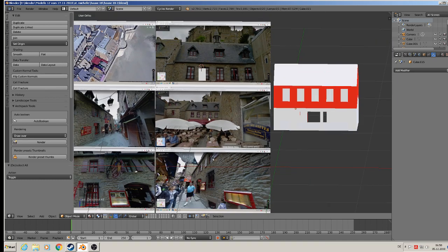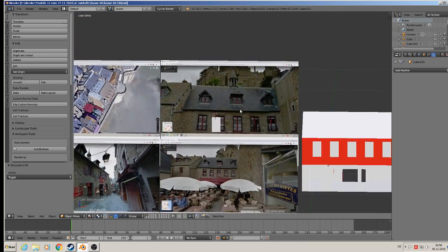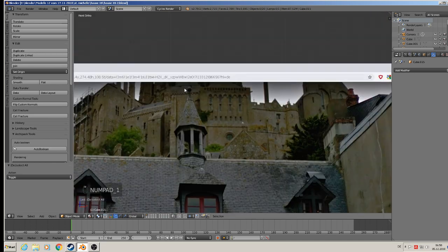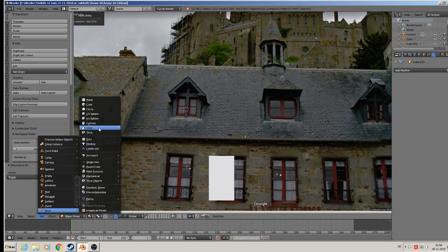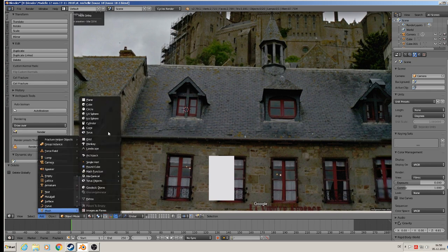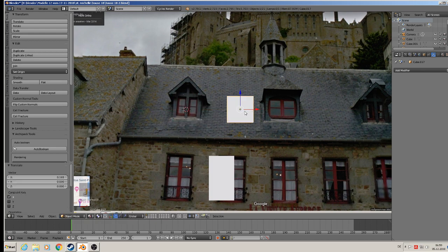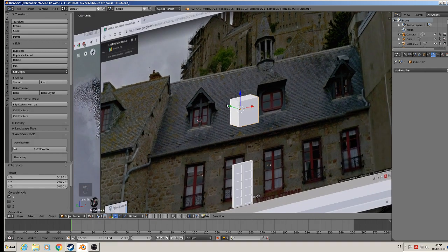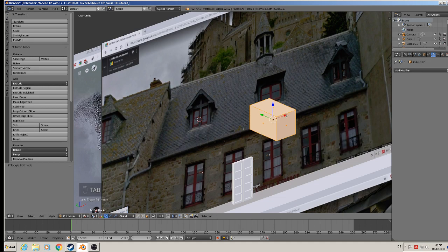So we need this rooftop style there. Here 3, and on the other side 3, and the middle one is different from the ones on the side. Okay. So we start again. Add mesh, not plane, cube like ever. Add mesh, cube, scale down, and we have that. Then we need a roof on. So at first we scale Y, then we get into edit mode, Control R, make a middle loop.